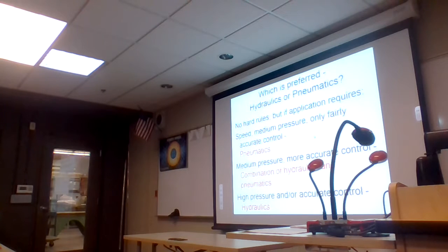Which is preferred, hydraulics or pneumatics? Well, you all know hydraulics deals with pushing confined liquids, and you know what pneumatics is. It's the use of compressed gases, or primarily air, but it could be almost any gas. There are no hard and fast rules, however, I will tell you this. Speed, medium pressure, only a fairly accurate control, usually pneumatics. Combination, high pressure or accurate control, usually hydraulic.